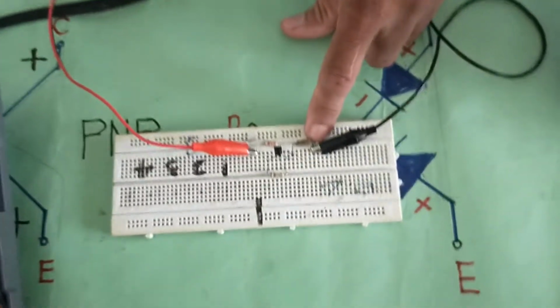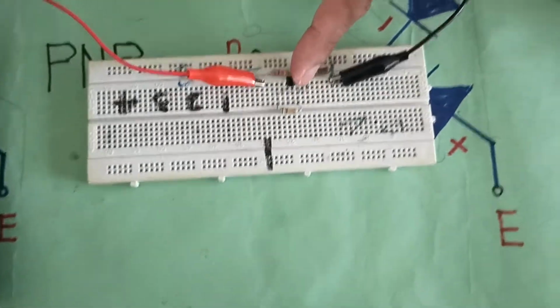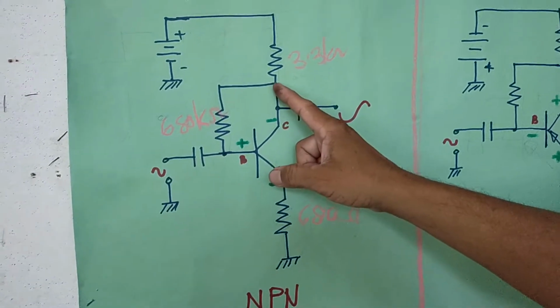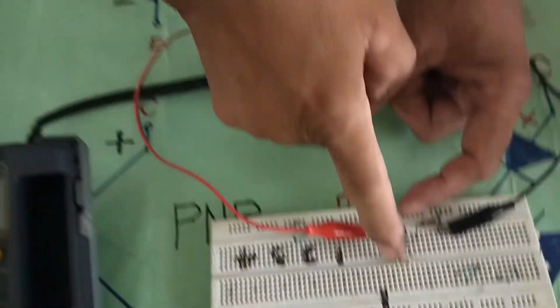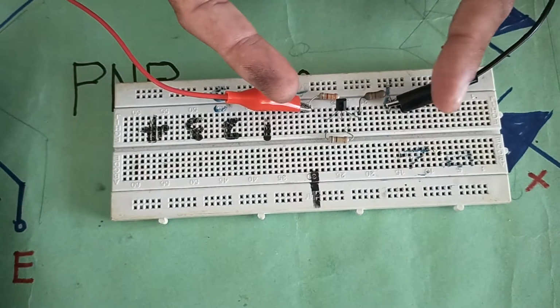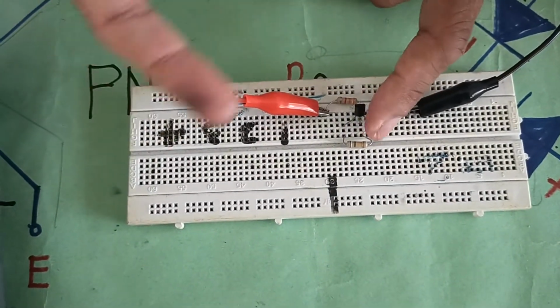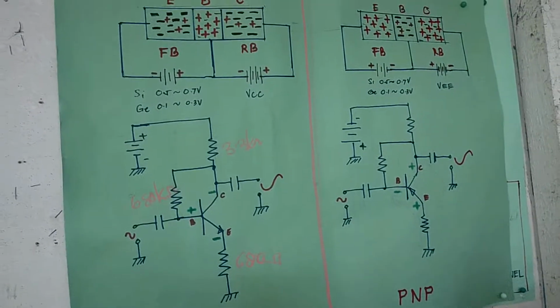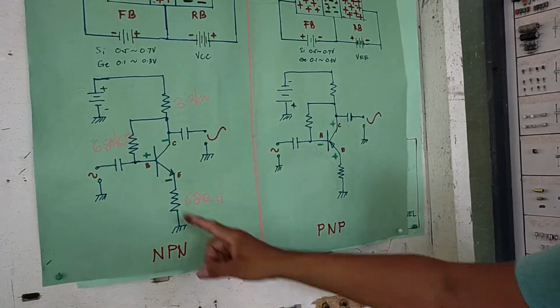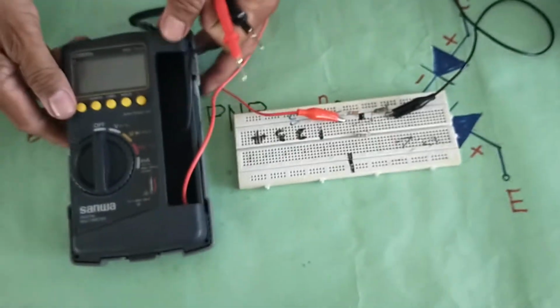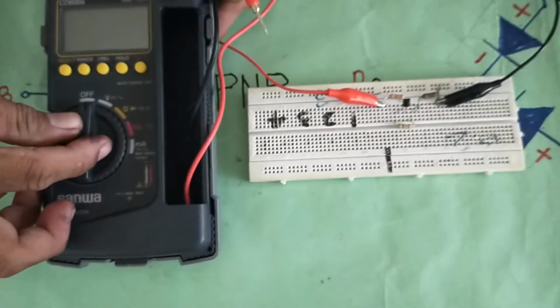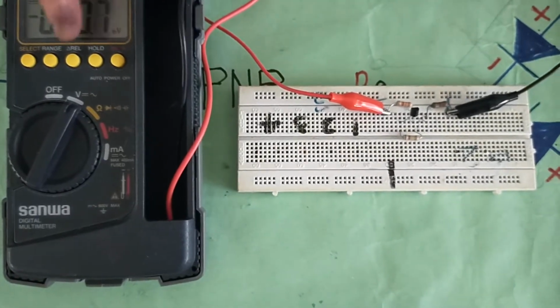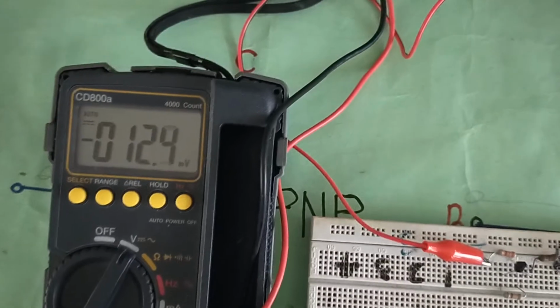So, here, this resistor, 680 kilo ohms, is connected across the base and collector. So we have here 680 kilo ohms with colors blue, gray, yellow. Okay? So let us now measure the voltage across the base-emitter junction. Remember that it is forward biased. So again, we will set this digital multimeter to voltmeter DC. Okay, we have here the DC symbol.